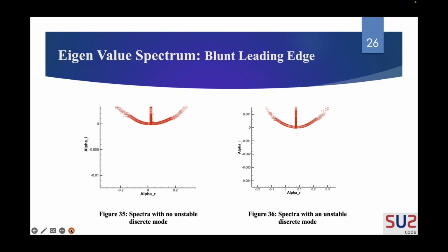If the eigenvalue spectrum is plotted for more locations and for appropriate frequencies calculated using the formulas, eventually we can obtain a plot very similar to the one that I showed in the second slide. That is the plot between the frequency and the local Reynolds number, which would result in a banana shaped curve, which would tell us about the unstable points and the stable points.